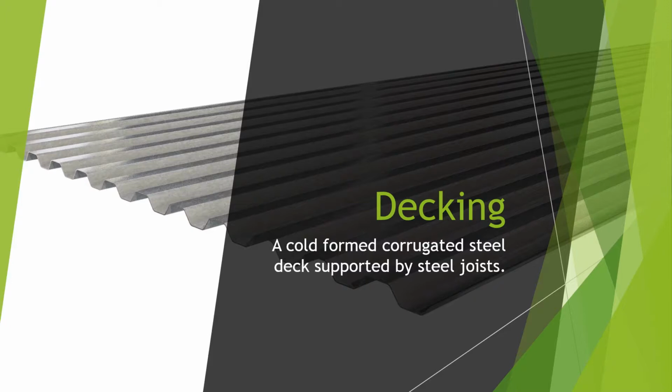How can we be safer, do you think, when erecting and working with decking? So what kind of things comes to mind? First off, yeah, we got a buddy system. So never handle that decking by yourself. Second, never leave open holes unless they're labeled and a physical barrier is around them. If we got something there telling us it's a hole and there's a physical barrier where we can't get through, we're not going to fall. Never work in high winds.